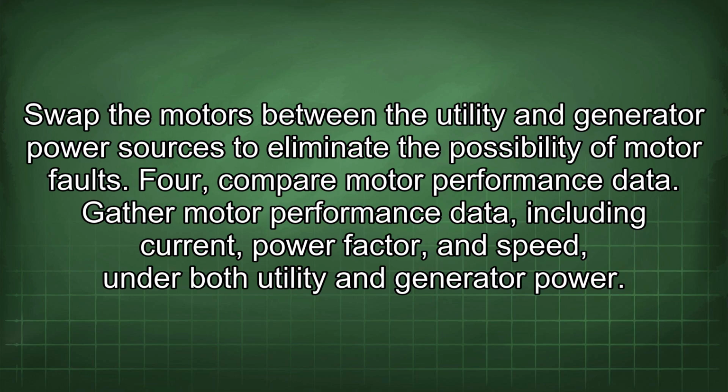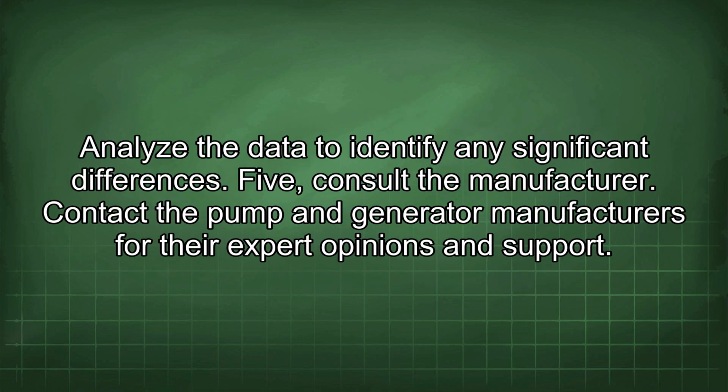4. Compare motor performance data. Gather motor performance data, including current, power factor, and speed, under both utility and generator power. Analyze the data to identify any significant differences. 5. Consult the manufacturer. Contact the pump and generator manufacturers for their expert opinions and support.